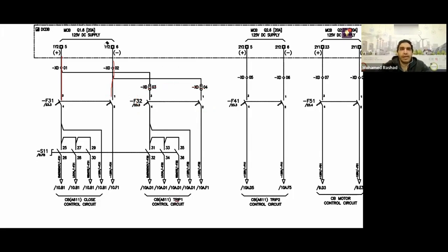Great, okay, now I have taken the positive and the negative. I first connected them to the MCB as we agreed. Of course, the positive and negative are coming from an external circuit. How did you know it's from an external circuit? We knew through the fact that this is the box with the dashed line, and inside this dashed line is another box that is half black and the other half white. So this means that it is remote or SCADA.